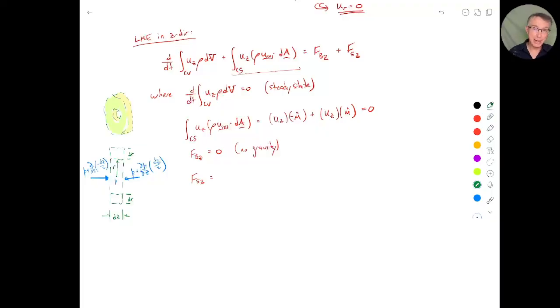So let me draw a positive shear stress on the outer face. That positive shear stress will act in the positive z direction. So that's a positive radial face acting in the positive z direction. If you don't know what I'm talking about there, you need to go back to your strength of material notes to understand the sign convention for shear stresses. But that shear stress would be tau rz. It's the shear stress acting on the radial face pointing in the z direction.